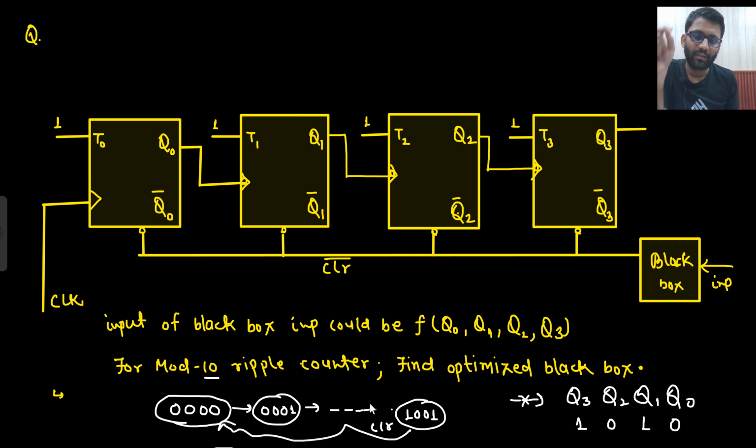Okay, first question I am writing: the first state that I don't want, that is 10 only. 1 0 1 0. And what I am doing, up counter. In case of up counter, I will always look at ones only. So which input am I writing? Clear input? No, I need clear bar input. If I need clear bar, I will always look at ones only.